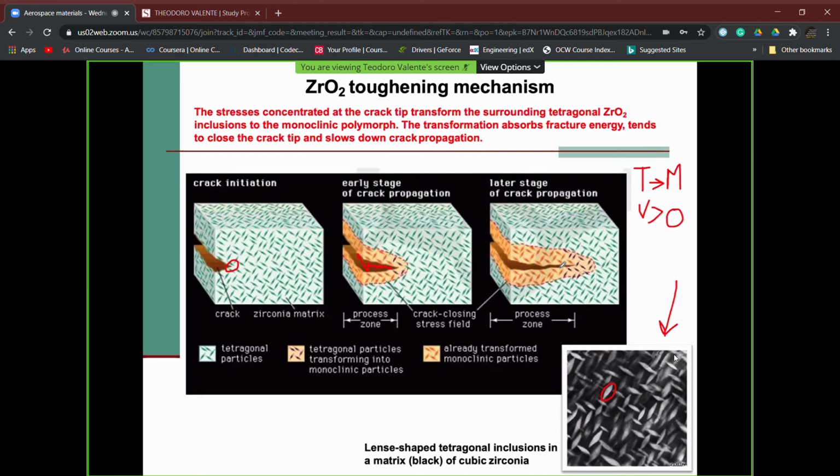We say that we can expect, and we have it, for partially stabilized zirconia, where stress concentration is going to activate a toughening mechanism, reducing the crack length, we do have a higher value of fracture toughness of the material, even though it's an apparent fracture toughness because it is related to the closing of the cracks.